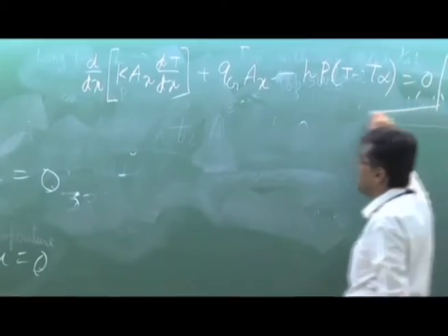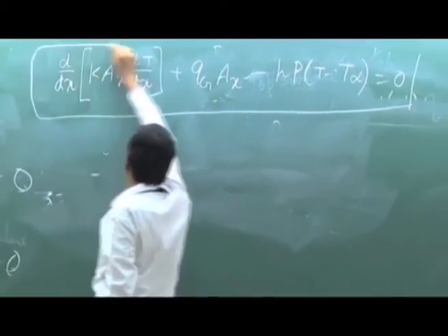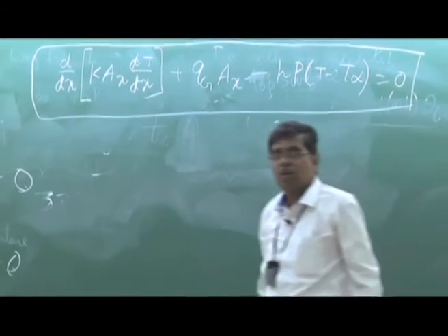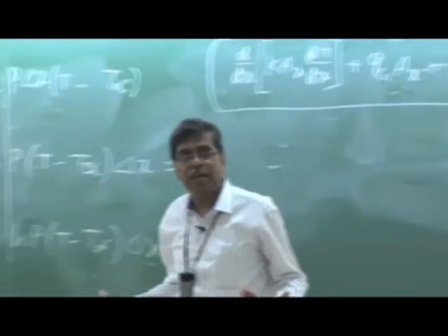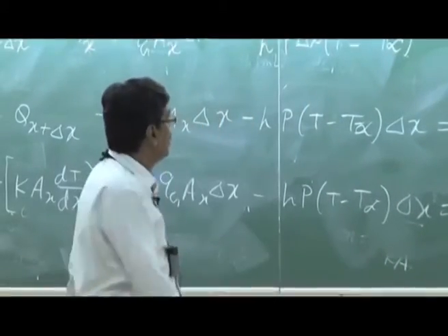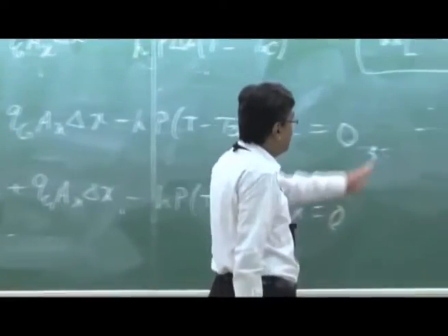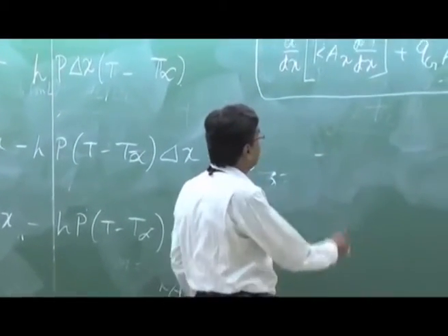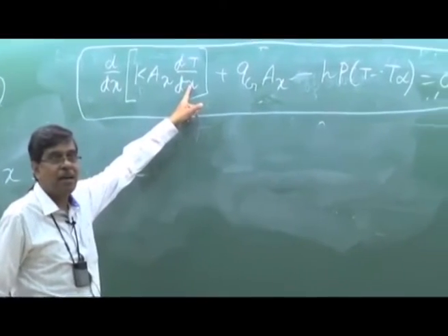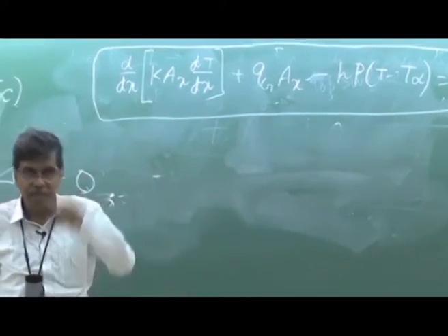And this is precisely the expression for one-dimensional heat conduction with generation of thermal energy and lateral convection. Heat is going out laterally. Now here, in a plane geometry, now in cylindrical coordinate x is R, cylindrical rod, cylindrical wall.